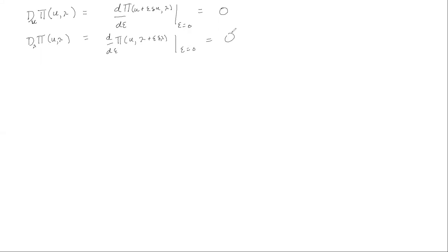So there are going to be two equations in our weak form. One that governs the behavior of the displacement and one that governs the behavior of the force, lambda, required to enforce the displacement constraint u naught.